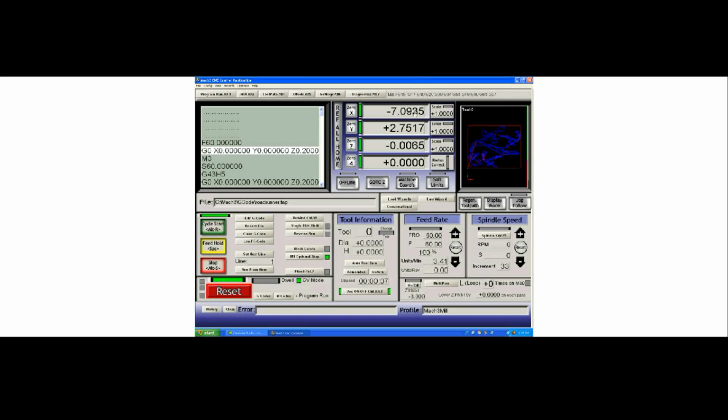will begin to move, and you can see that my speeds and feeds are probably not adjusted appropriately for this particular program, but eventually you'll see a green line trace out the path of the Roadrunner, and your motors should now be feeding themselves at that speed in that area. That's it for a general setup of Mach 3. For the beginning user getting their motors running, that should be all it takes.